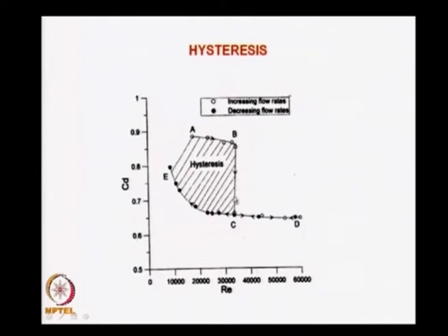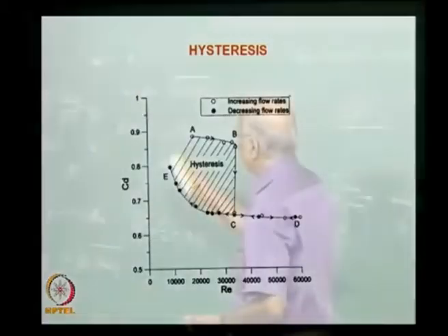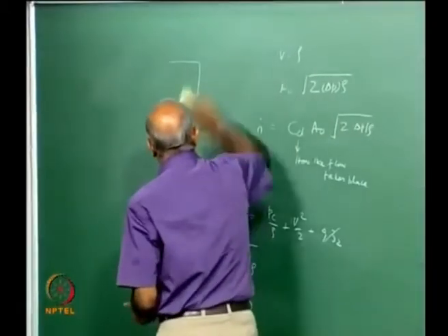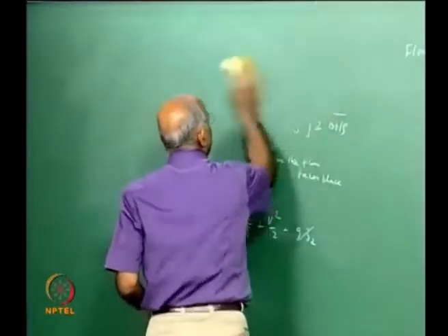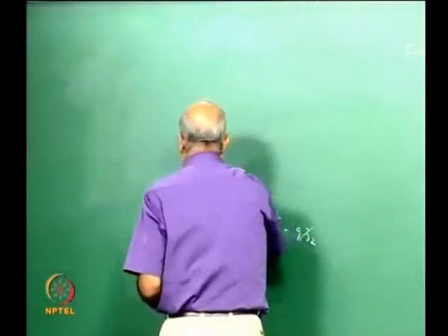Somewhere cavitation starts, it begins to separate, I go over here, it is still separated, and now when I start reducing the pressure or reducing the velocity again, it goes like this, but the memory of the separated flow lingers on and CD decreases, it never comes back to this. That means even a small thing like a shower head injector, which is nothing but an orifice like this, is not that straightforward. And what happens? Let's try to put this down.